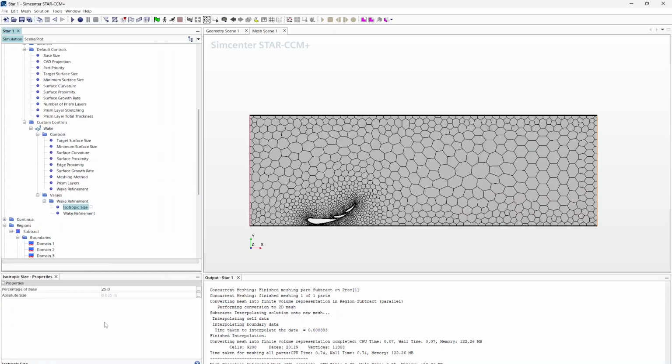So we will just hope that that's correct. Again, we don't need to be 25% of the size on the airfoils. We can probably get away with around 40. For 3D sims, this is much more important. We could probably leave it at 25 for a 2D sim, as it will still run really quickly. And we'll change that growth rate to 1.2 instead of 1.3.